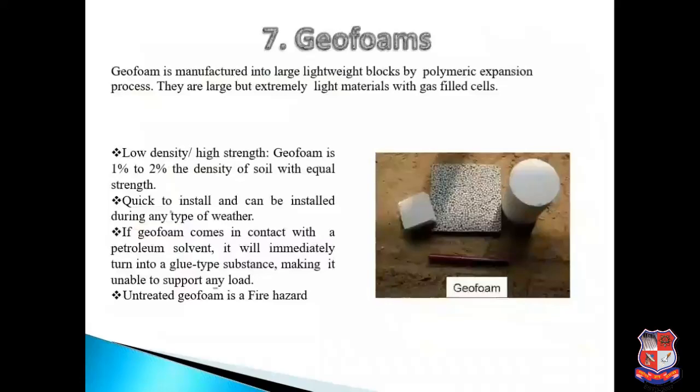If geofoam comes in contact with a petroleum solvent, it will immediately turn into a glue-type substance, making it unable to support any load. An untreated geofoam is a fire hazard, so it is very dangerous to use geofoam. So it is mainly not used. You can see geofoam of different shapes in the image.